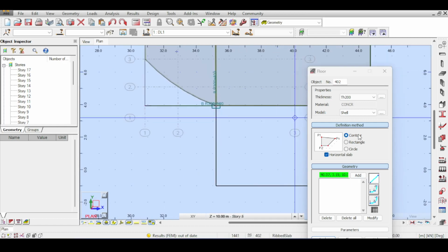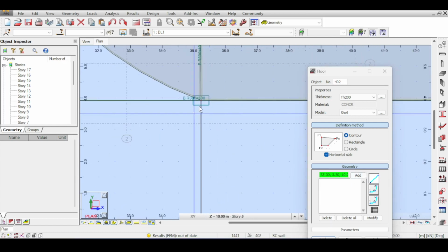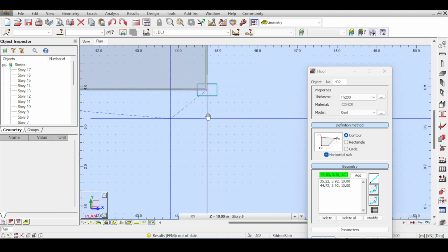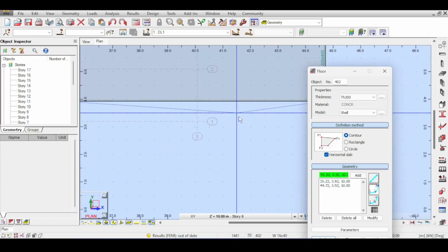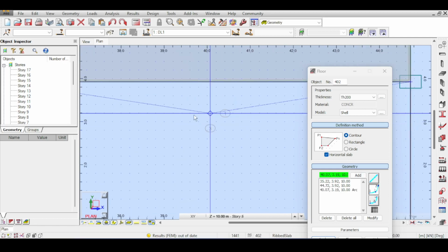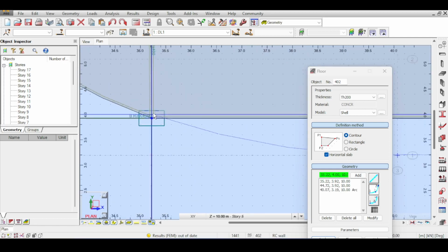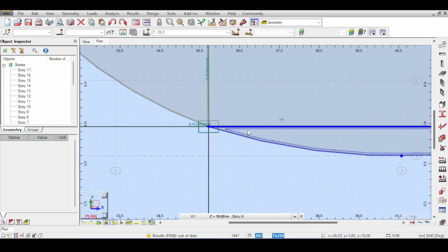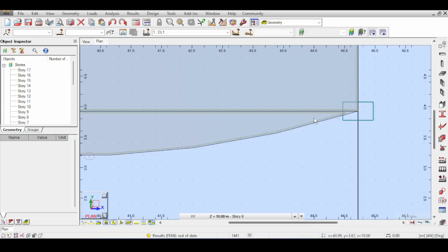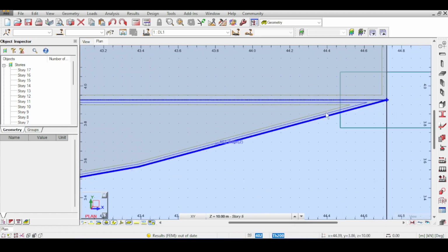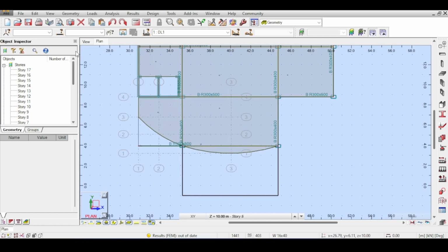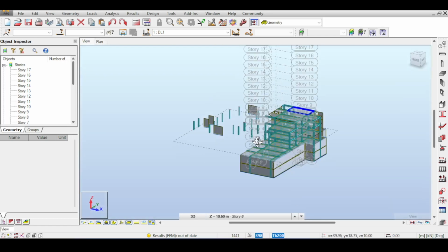Now for the second one, that's going to be easy. Contour. The first one is a line, of course. That's not a big deal. And the second one is an arc with its center already defined. I'll click here for the middle point, and I'll click here for the end. And that's the approximation idea I got. I don't know. This will cause mayhem for the finite element method here, especially here. And I will talk about this later. Check out my Slab series if you want to understand more about meshes. But let's go back. Let's take a look if it looks good.